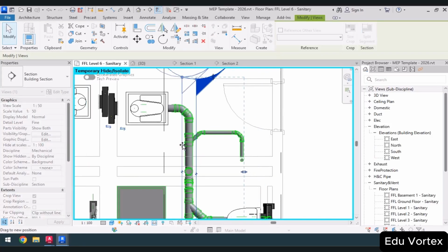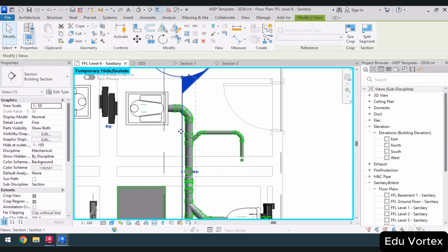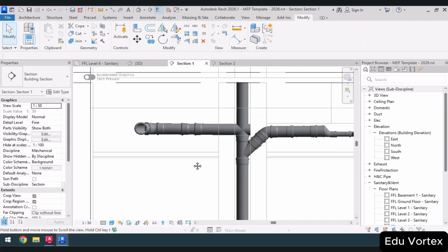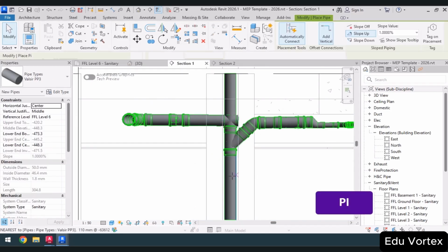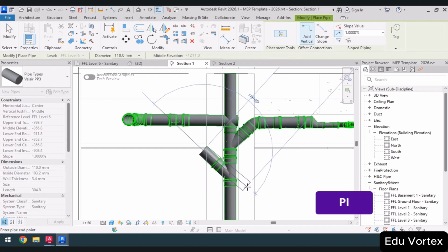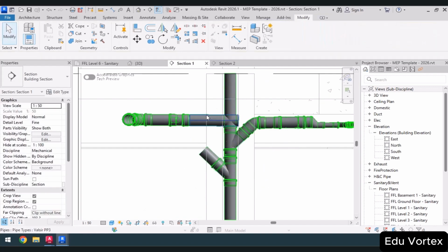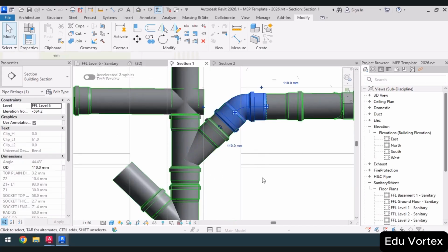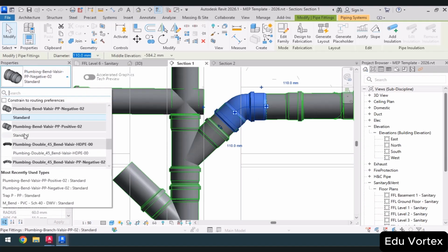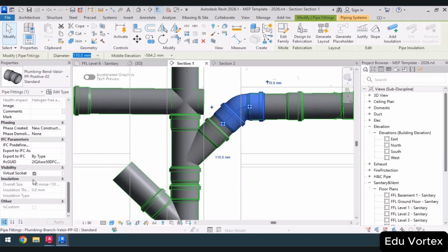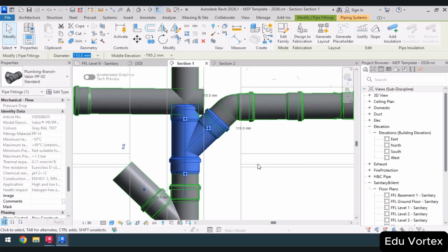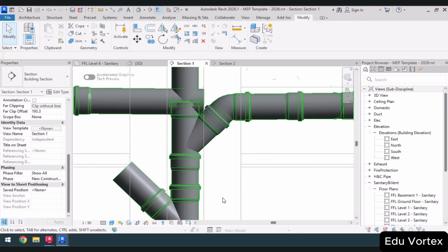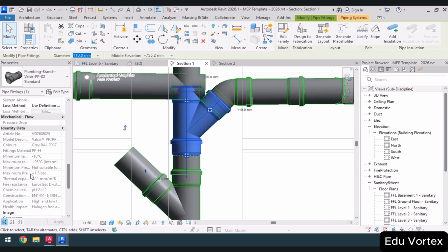So now that we have adjusted this side, let's connect it to the riser. Right clicking, go to view. I need to take a branch from down here using the pipe command PI, setting a 45-degree angle as much as possible. I will bring these connections closer together so that I can place an elbow here. For that, I need to rotate the first elbow to the correct direction, and then I will remove the virtual socket from this, and I will move this three-way junction as close as possible to the elbow so I can get it any closer. And then this.